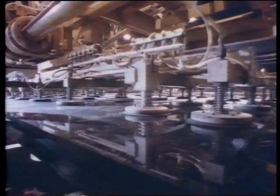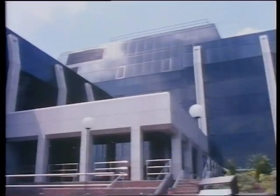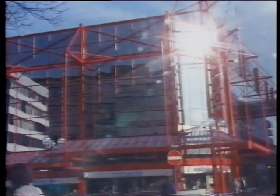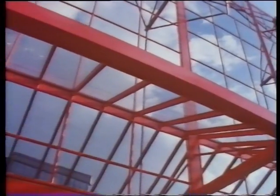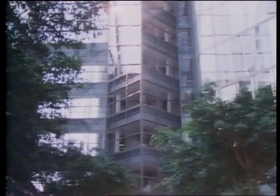Colour introduced either in the body or in the surface of the glass as a thin metallic coating. It includes heat-absorbing glass, such as anti-sun float glass. Glass to reduce glare and insulate against the excessive heat of the unfiltered sun. Or heat-reflecting glass, called sun-cool. Float glass which is reflective colour-coated on one surface after it's been made. Tinted or coated glass is as much to be looked at as looked through. Glass that looks good outside and feels good inside.